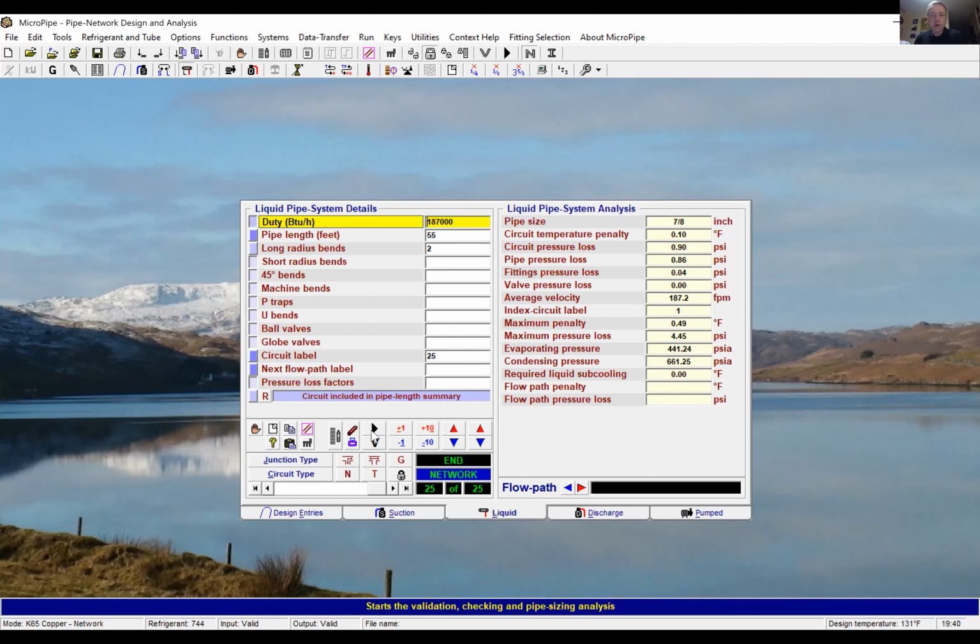It's quite good. The output's not saying it's going to give you a system that's going to work, but a design engineer might go through and, for whatever reason, want to have a lower penalty, or a little bit of consistency. As we all know, installation technicians put in pipework in the middle of the night, and if you're building up a big header system, once we've got that armaflex insulation around the pipes, you don't necessarily know what diameter it is. So I'd always look at high level pipework and try to have some continuity. It's a design friendly system for the installation technicians.